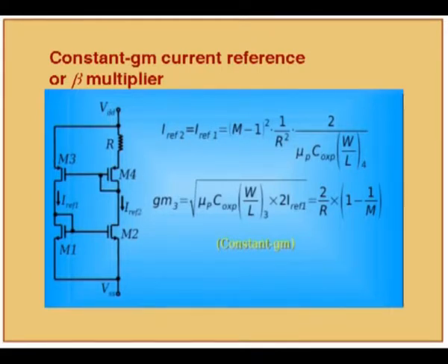Sometimes it goes above 100. So that's why we get a lot of variation. And the second thing is not only the matter of temperature. Process itself, suppose it's a poly resistor, if the doping in the poly changes, then the sheet resistance will change easily. So it's very difficult to achieve a good on-chip stable resistor.